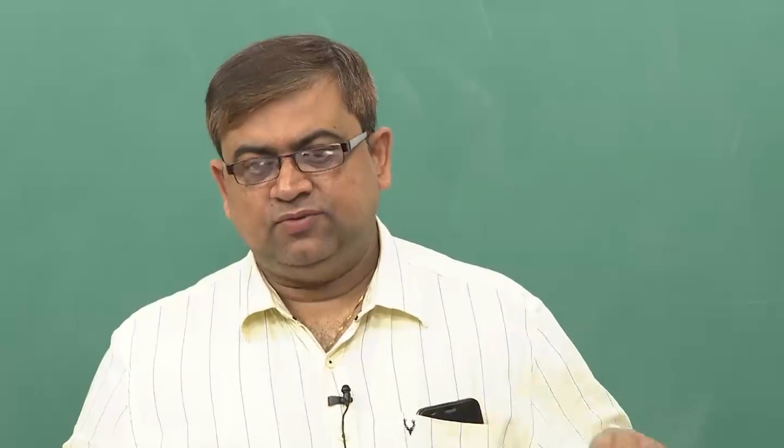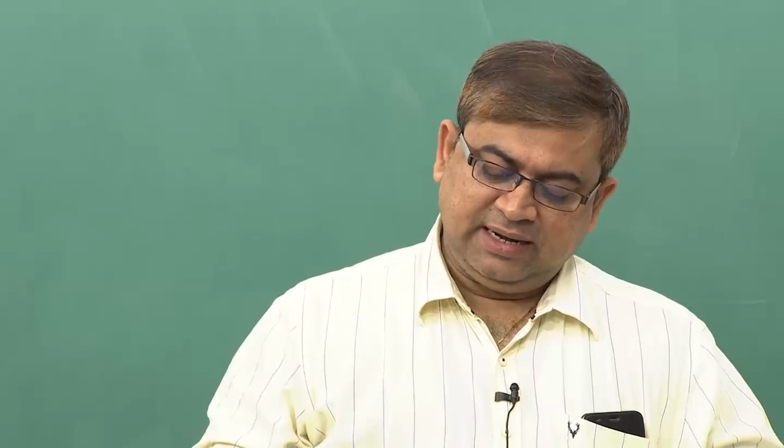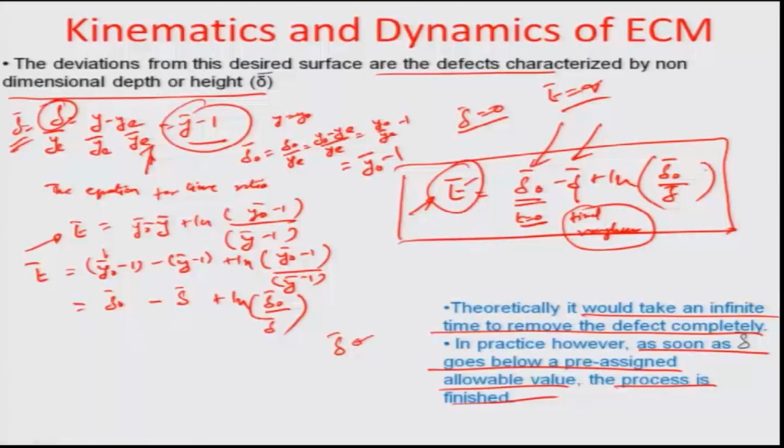It is of importance for the industry as well, what is the level of roughness up to which you can finish a surface. ECM is a self-leveling, self-evening process of an otherwise uneven surface, but it cannot go beyond the capacity of the process to do the self-leveling. This is the limit delta dash that you would finally arrive at, which is also known as the process tolerance in ECM. So, that is how you take care of this term called process tolerance in ECM.